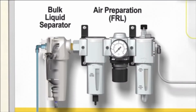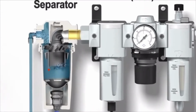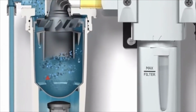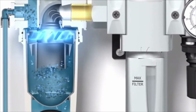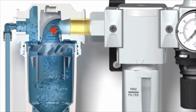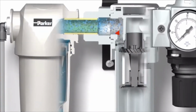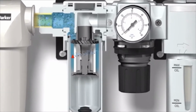Typically, the first unit in the air preparation system is what is called a bulk liquid separator, which circulates or spins the air using specially shaped vanes. The rapid circulation of the pressurized air sheds unwanted moisture due to centrifugal force. The next unit is a filter, which further removes particulate and moisture in a 2-stage process.